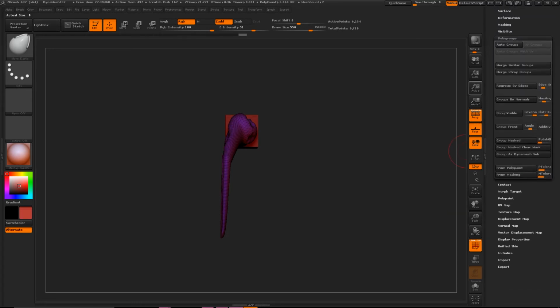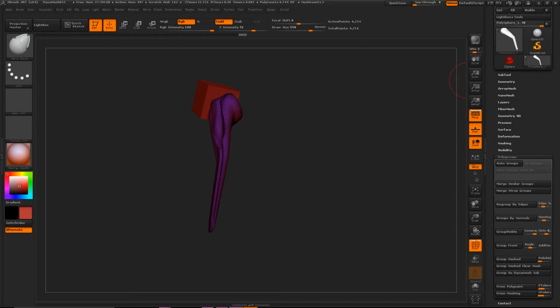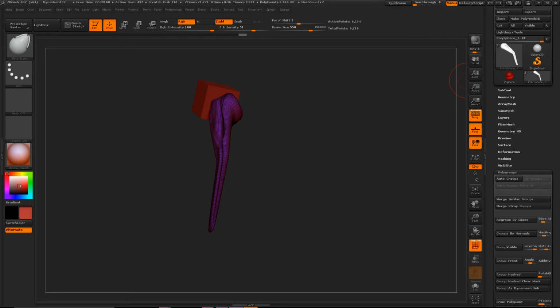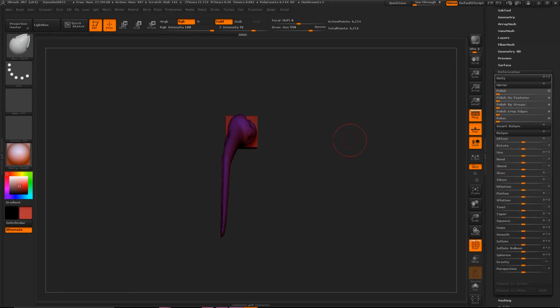As you can see, we have more important panels like the polygroups that we'll work later with a bit more detail. As you can see, when I activate the mesh, an element we'll see is the colors. Okay, these colors are the polygroups. The polygroups are a kind of selection of polygons that we can later apply to many things, whether selecting the elements to decide the material we'll use on the elements, or for working on an object on another program. We'll use these polygroups a lot. Here we also have this panel where we'll have the modifiers a little more directly that we can apply to the model.